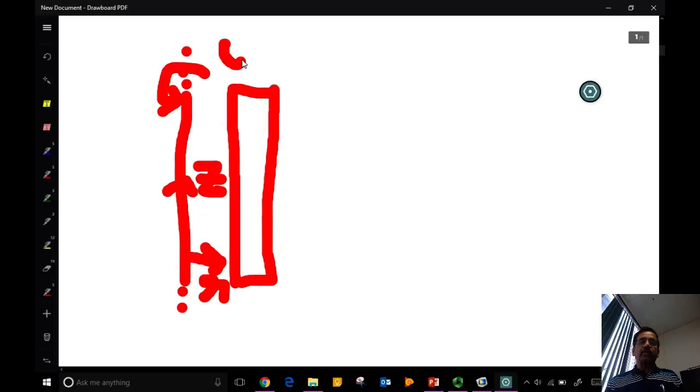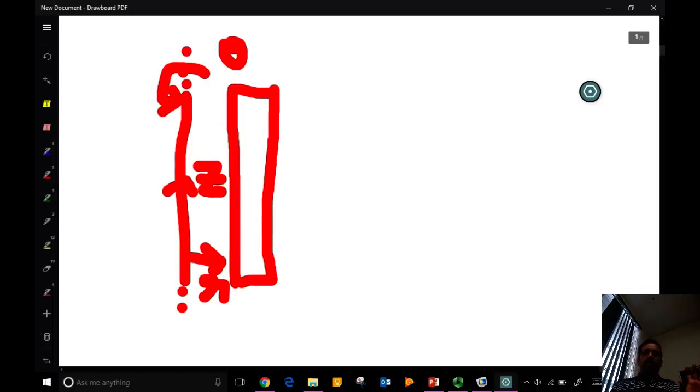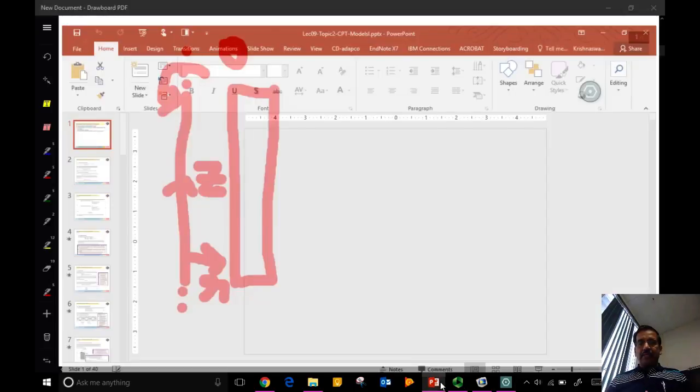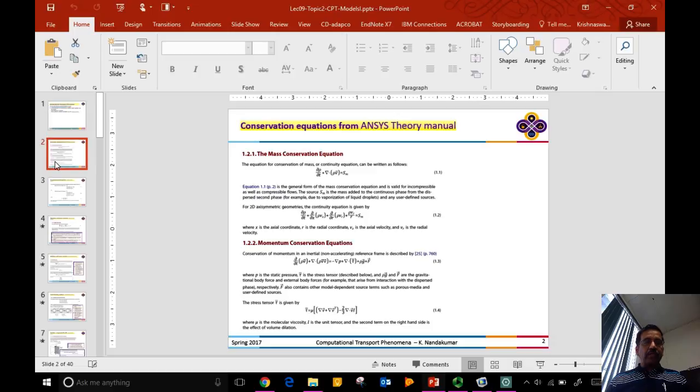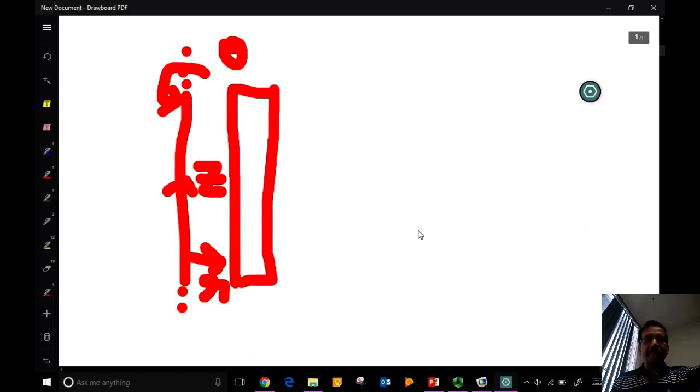So if you know cylindrical coordinates, you know how the Navier-Stokes equation looks in cylindrical coordinates. I will show you later when you go back to the PowerPoint slides. What I'm going to focus on now is how the flow would look, to set up the problem for a domain that is a concentric cylinder completely filled with liquid. This device is very important, and this problem was studied by Taylor in 1927. I probably showed you in the last lecture a lot of flow patterns computed in this geometry.